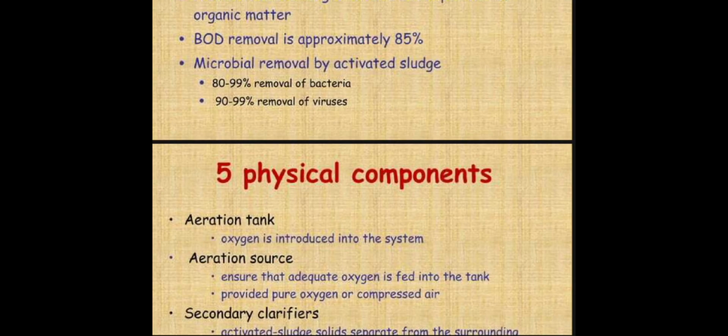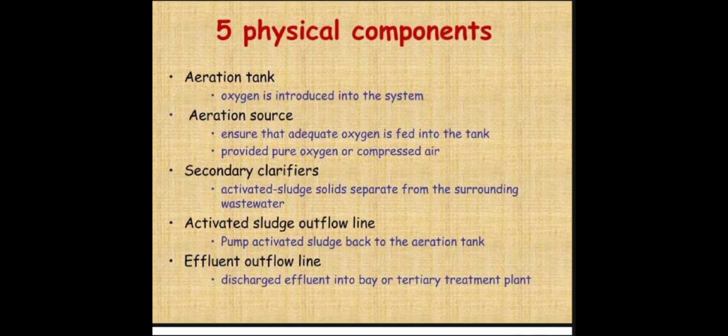Okay, in this process, see these last 2 points. BOD removal is approximately 85% of BOD will be removed in this process. Okay, microbial removal by activated sludge. See here, 80 to 99% removal of bacteria. Next one is 90 to 99% removal of virus.